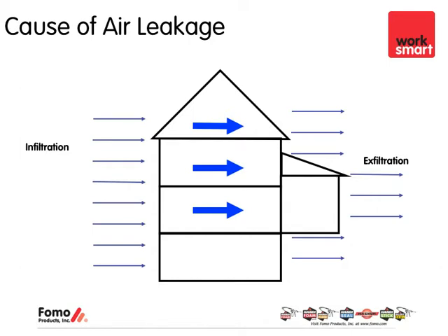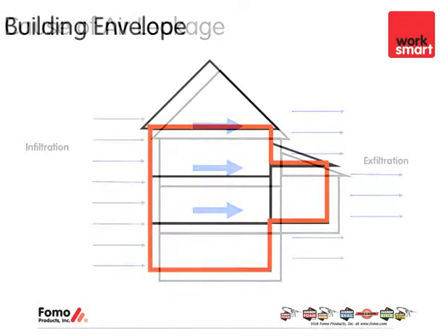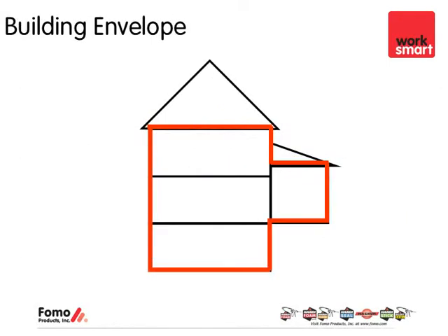In this case, you would feel the air leakage coming from your electrical outlets. You could find it coming out of your windows. The combination of wind and stack effect could be happening if you've got a very windy day on cold temperatures as well. When you're looking at the building envelope, the goal to determine if you have a solid envelope with minimal air leakage is, can you take your pen and draw a consistent line through the outside of the building without picking up your pen, meaning that all building materials have been joined together, all holes have been filled.